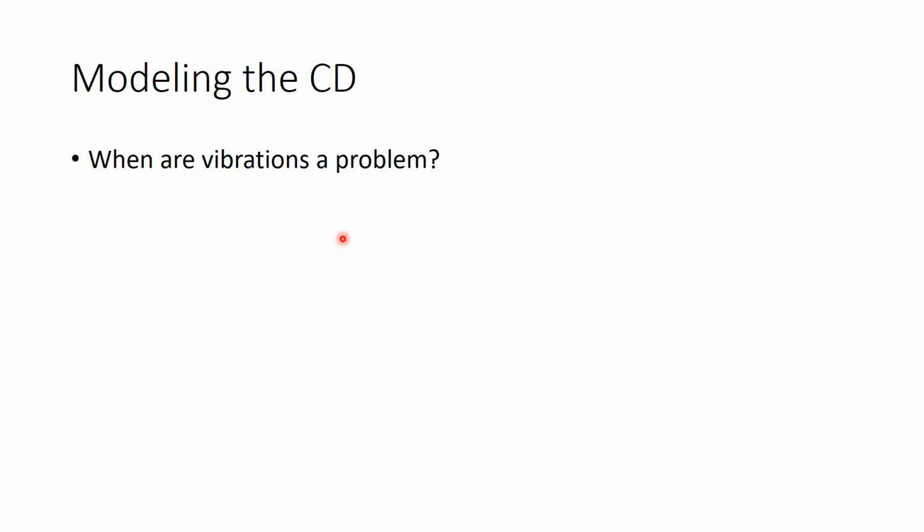You'll need to look up what the range of rotational velocities of a CD can be. There's a link provided on the assignment. And then compare that and solve for the modal frequencies as a function of the speed with the pre-stress, and see if there are points where those cross, and then tell us what that means for the likelihood of failure.